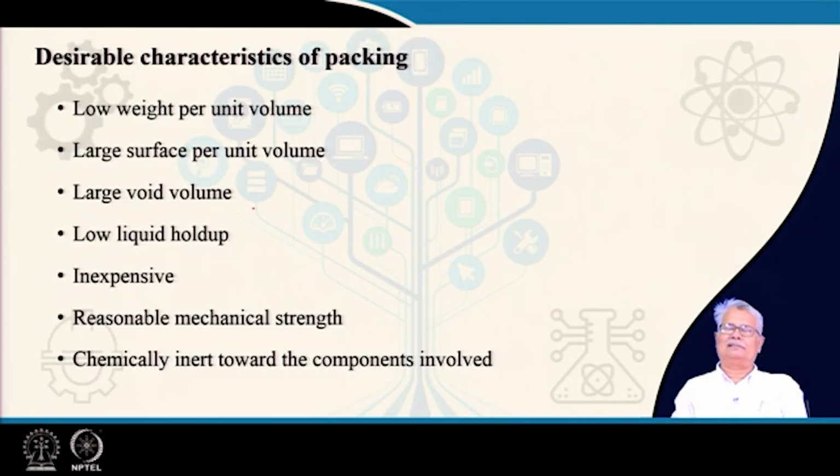Low liquid holdup. Yes, low liquid holdup is basically something we desire. We already said that we will always prefer a thin liquid film wetting the surface of the packing. So, naturally, if you have a thin film, you would have a low liquid holdup. So, they are complementary qualities. Inexpensive, it is too obvious to say why we require something to be inexpensive, because the material required for packing, usually the volume is large, the quantity is large. So, it should not be too expensive.